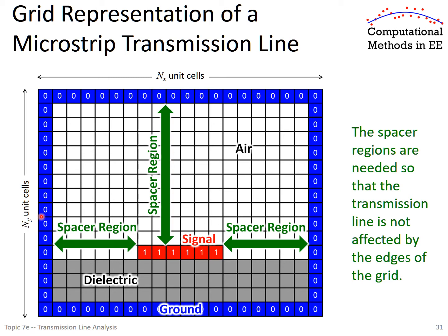Now we will also make it grounded all the way around. And this has to do with the fact that due to our staggering, our boundary conditions are not symmetric, so we have an asymmetric problem. And if we were to calculate the electric fields, they would look slightly pulled to one direction. So what we can do is just simply surround everything by metal, and that makes our problem look symmetric. It does not make it more accurate, it just makes it more visually appealing.